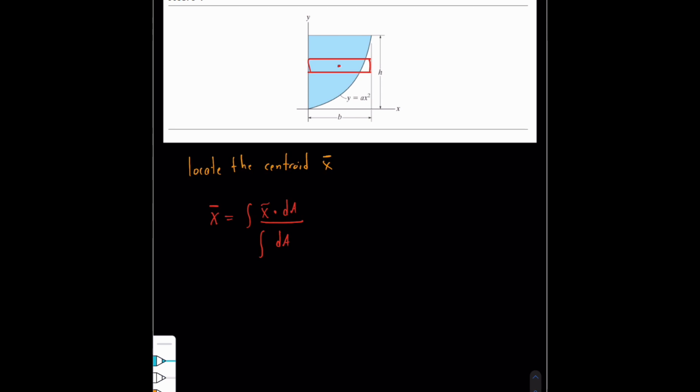I could use this same drawing to do everything I need. Now, recall that x2 is going to be x divided by 2 here because we're at the center of the x. Dividing the x-axis in half gives us the centroid in the x direction. And obviously, y is going to be a constant right here. Now, that makes our x2 equal to x over 2.